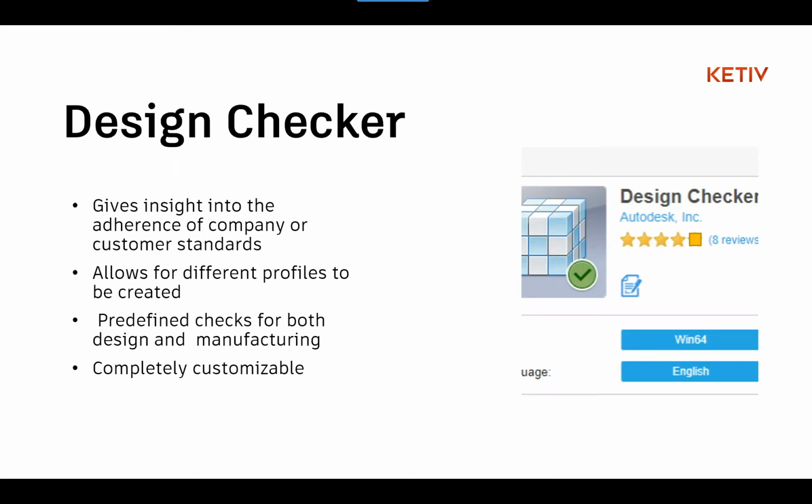Create that profile to make sure that the users adhere to a specific standard, and then have it running in the background so that the engineer can see in real time whether his designs meet those standards or not. Right, so it's a really neat tool. Like I said, there's a lot of customization that you can build into the Design Checker app. It does have a connection with iLogic. So if you are using iLogic at the moment, this is just another huge benefit to those users as well.